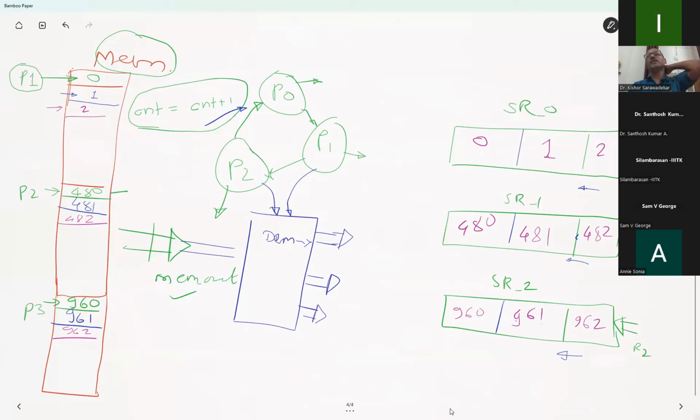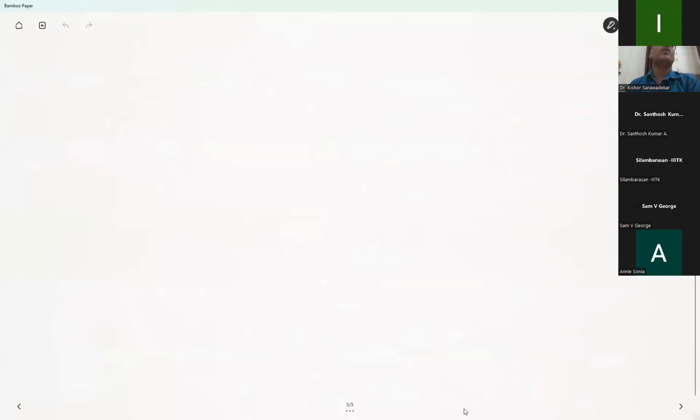So this is typically, if you look at what all we used: counters, then shift registers, then the basic information was available in memory, then some kind of state machine to increment the pointer timely 0, 1, 2. That is nothing but a 2-bit counter, mod 2, right?